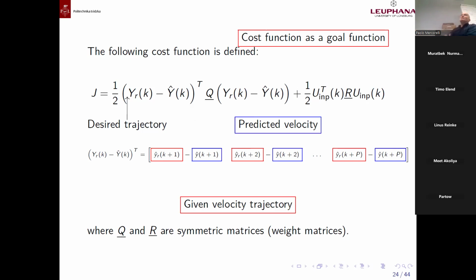For some systems that could be okay, but for instance in the case of fast systems, which need speed, we need to answer in everything, observer, controller, and also the optimization method, in microseconds. So it is a good idea to include this limitation implicitly, the other word being explicitly with inequalities, in the cost function.